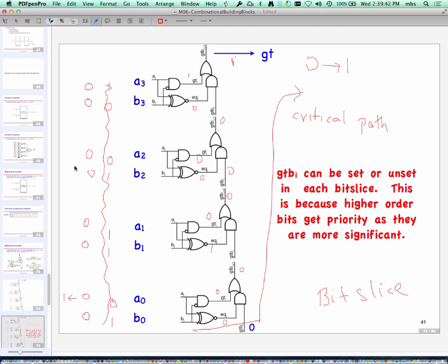Nothing else changed at the inputs. So that means the effect out here had to flow through all this logic and then affect this guy out here. And therefore it is going through this long path, and that's the critical path. And we'll see the same kind of thing in our arbiter design, long critical path. So these bit slice designs often exhibit these kind of paths which go through all the bits. They add to the delay, but they are a compact design. They're a modular design because I can easily create designs with an arbitrary number of bits.